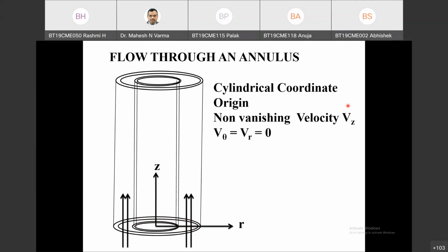So this is exactly similar to the previous problem. In the previous problem, we had only z velocity, and v theta and vr were equal to 0. So altogether the shell balance approach and the shell will be exactly similar to what we took in the previous problem. So what will be the dimensions of the shell here? And whether Vz is a function of theta, R and Z. Vz is a function of theta, R and Z. Here, roll number 93, Sai.